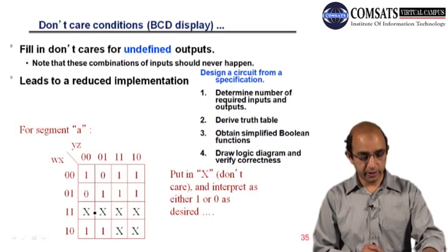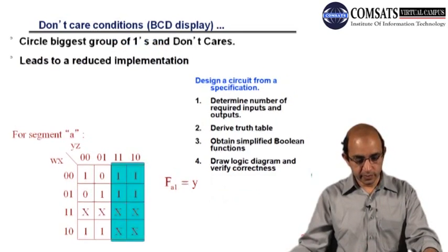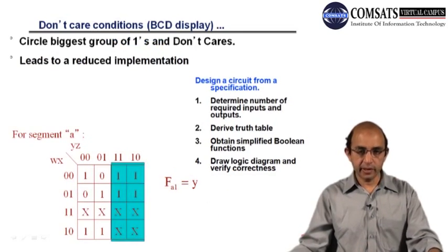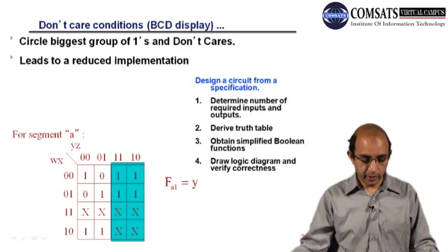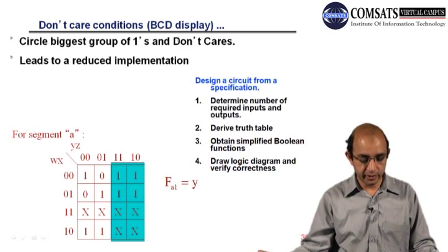By introducing the don't care conditions, we can have the maximum possible simplification. We normally introduce don't care conditions in order to have more simplification.